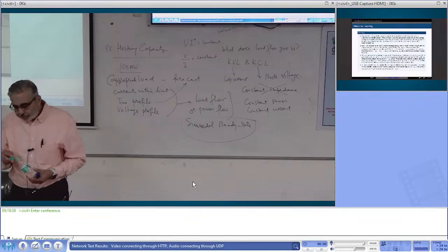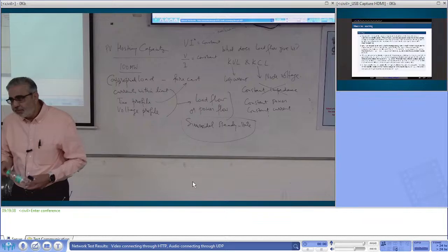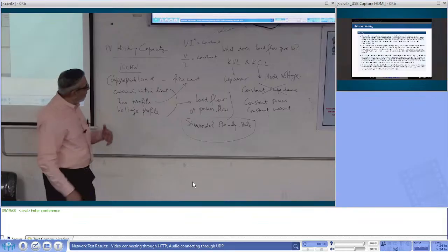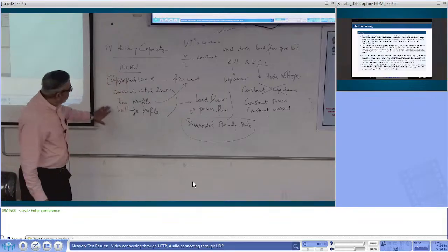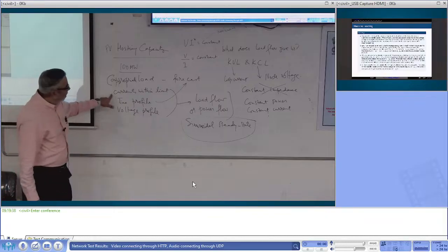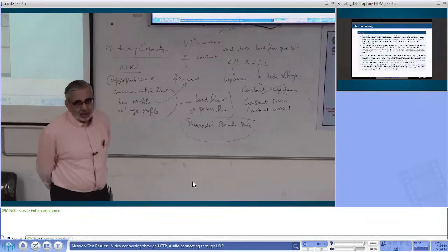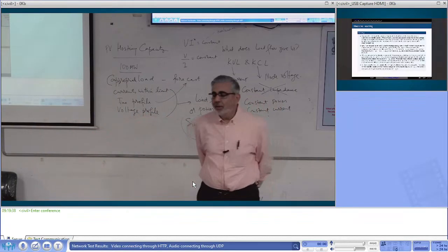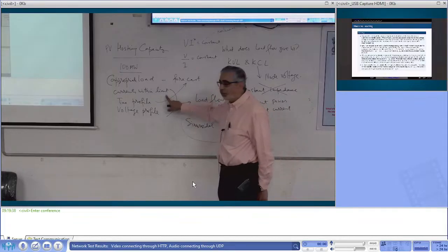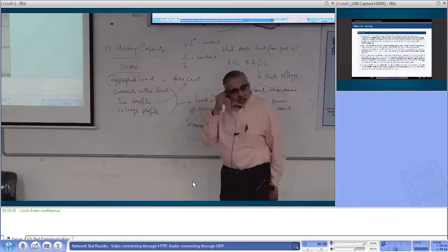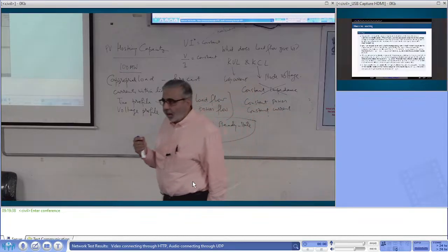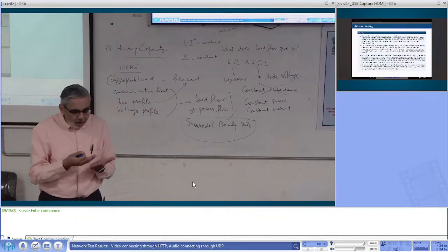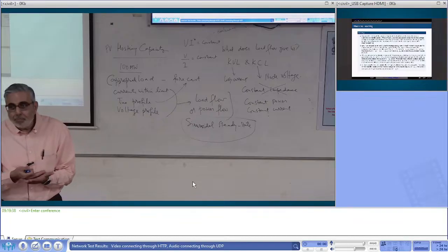I want to say that 100 megawatts is the hosting capacity. Then why do I have to do multiple load flows and guarantee that in each of those load flows my voltage profile is preserved and the currents through the cables are within safe limits? Many times current is the limitation: voltages are alright but currents are very high and it's unsafe. So if I make sure of both things, why do I have to make sure for multiple cases?